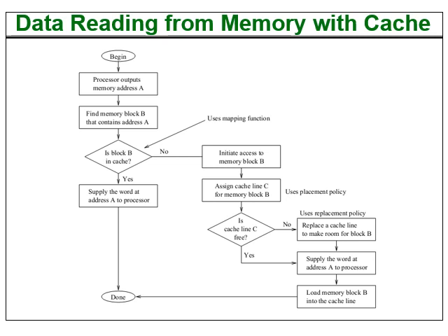Now let us assume that the cache memory has only 32 words stored in it. Obviously it is smaller than main memory. So if the cache memory has 32 words stored in it, that means the cache memory needs a memory address of 5 bits. But the CPU is generating a 7-bit address, but the cache memory requires a 5-bit address. So your first problem is how to map that 7-bit address into this 5-bit address.